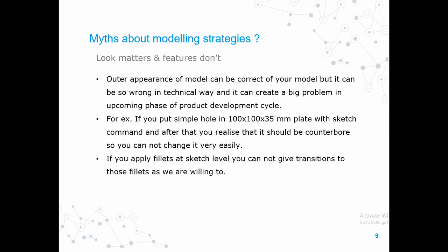And the last one is about the difference between looks and features. This is very important to understand for early learner students who have little to no experience in design. For example, if you put a simple hole in a 100 by 100 by 35 mm plate with the sketch command, and after that you realize that it should be a counterbore, you cannot change it very easily. If you only concentrate on the look of the model, you can put yourself in trouble.